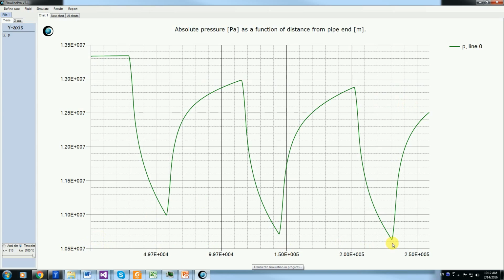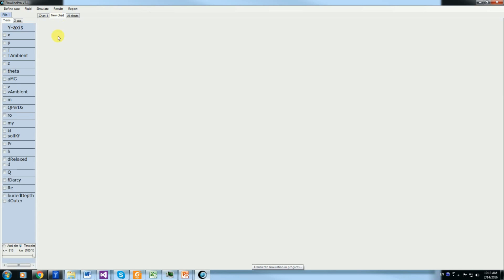we are way above 10 megapascal, which is much more than the contract specifies. So we can operate the pipeline like this for a very long time. And also if we for some reason took out quite much more some of the days, that should also work quite well. We would still be able to keep our guarantee. So the storage capacity of the pipe is very significant for some types of operation.